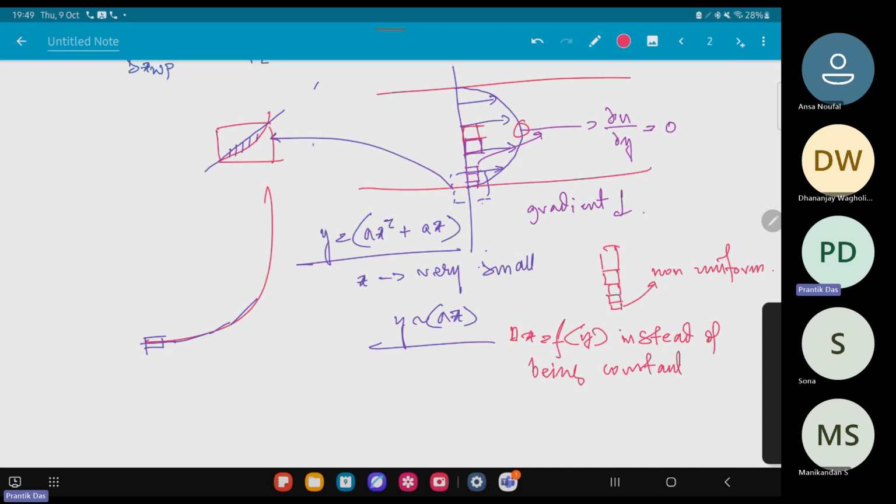So this is also known as biasing in different solvers like ANSYS Fluent. They will ask for something called the bias factor in order to find the ratio between the largest and the smallest cell size, and also ask for the growth rate. So those things should be taken into account. By reading the user manual, you can know what the parameters are and how you should tune them in order to get a legible solution. Okay, so coming back to the exponential scheme itself.